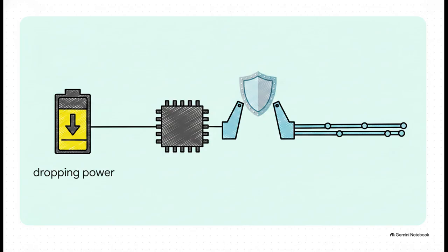To explain the working here, by going high impedance, the chip basically acts like an open circuit. It completely unloads itself from the bus, ensuring that its own struggling low-power state doesn't act like an electrical anchor dragging the rest of the healthy network down.